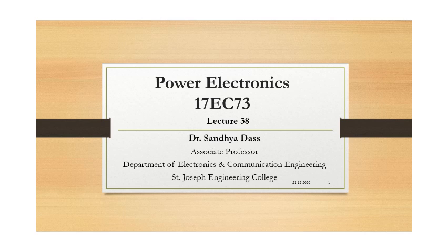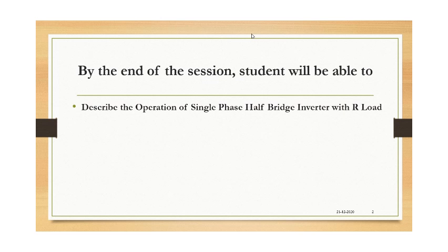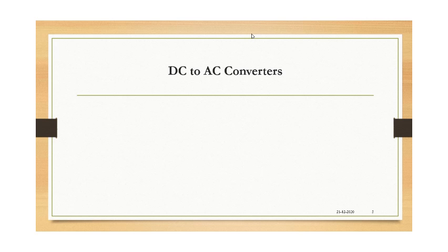In this session, we will be first discussing the different classifications, that is inverter classification, and the simple half bridge inverter, its working with the R load. So by the end of this session, you will be able to describe the operation of single phase half bridge inverter with R load.